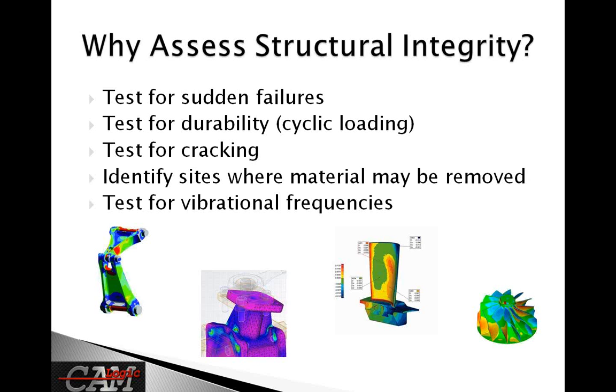First of all, we want to be able to test in advance of putting a component into production whether or not there is any possibility for sudden failures. The sudden failure may occur when loading conditions cause stresses at a given location to exceed the yield stress. Then plastic deformation can occur, and that can lead to a sudden failure.